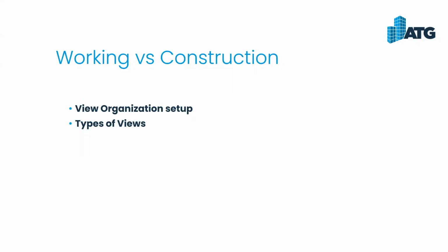The coordination category will contain any views for coordination with other disciplines. So this will help on the MEP side. If you're working on the mechanical HVAC, you're putting in your air terminals, but you're also going to want to know where light fixtures are located within there. So with that, we're able to see, again, multiple disciplines within a coordination type display.